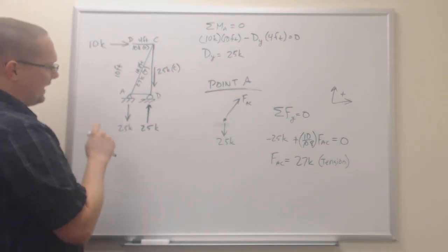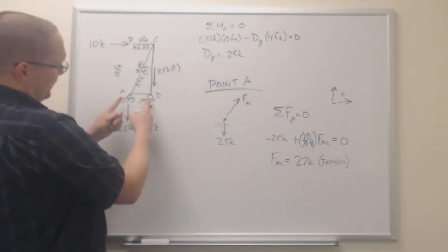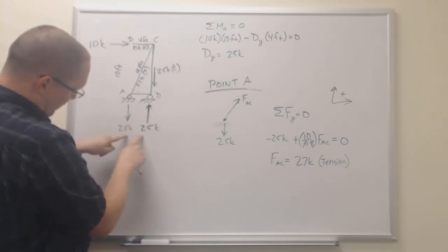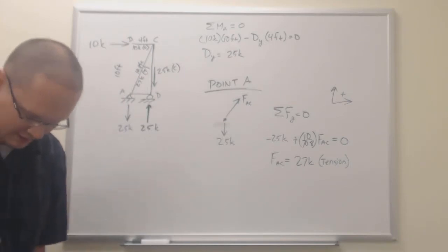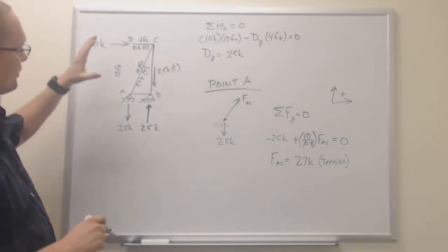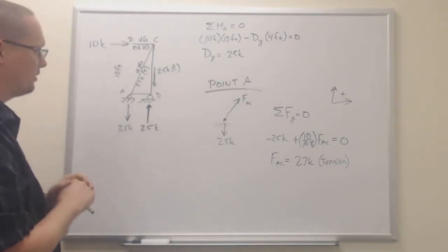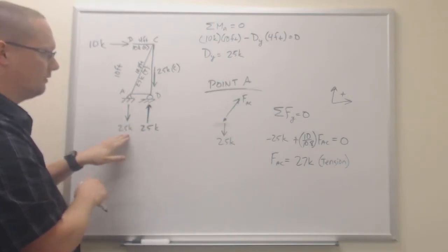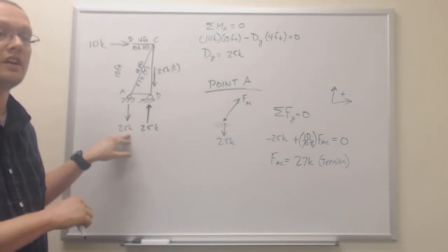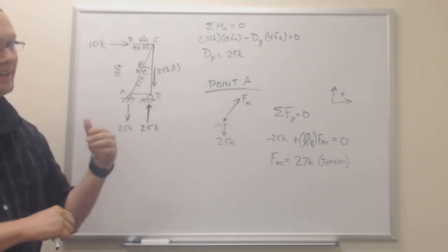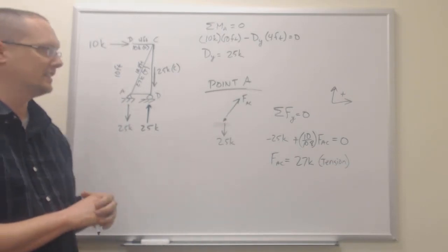So not only that, but when the wind is blowing, the closer these two get together, the more these reactions increase. Because remember, even though we have our force distributed over 2 separate shear walls, the distance is so close that our attachments to our foundation are quite a bit more. 25 kips compared to 8.33 kips in our previous example.